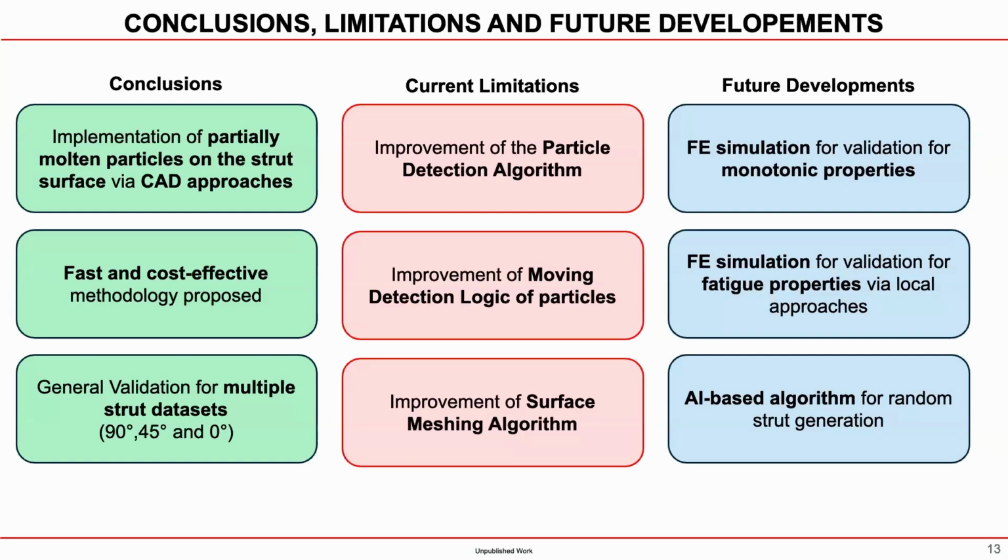Of course, there are still some limitations. We need to improve the particle detection algorithm, as well as the moving detection logic and the surface meshing algorithm. But most importantly, we need to do a real validation with respect to our ground truth, which are CT scans, with finite element simulation, either for monotonic properties or for fatigue properties. Simultaneously to this, we are also building an AI-based algorithm for random strut generation.